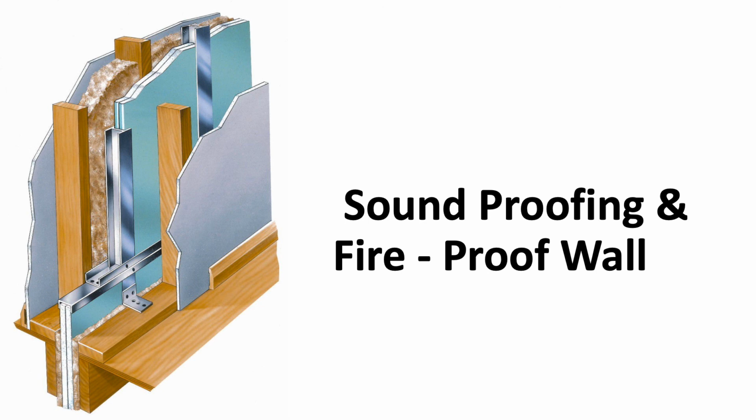All your commercial buildings are going to be built with 5/8 fire sheetrock for fire code. Now that's a 30-minute fireproof wall. If it's a corridor wall in a hotel or an office building, you may very well have one of those corridor walls, or maybe even both of them, to have 2 layers of 5/8 sheetrock on them. That gives you a 1-hour fire rating.